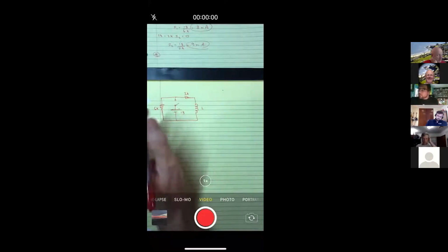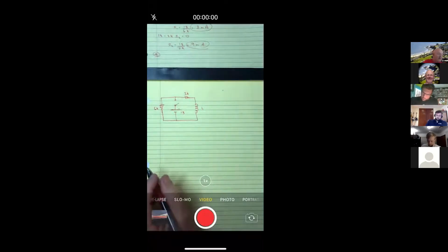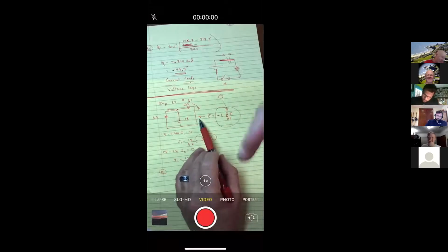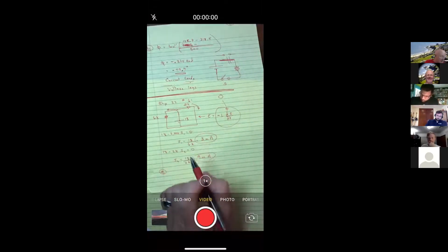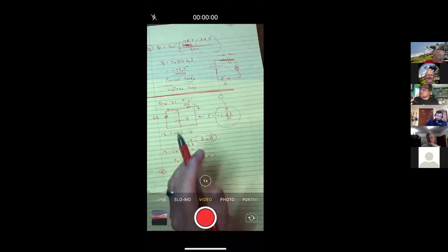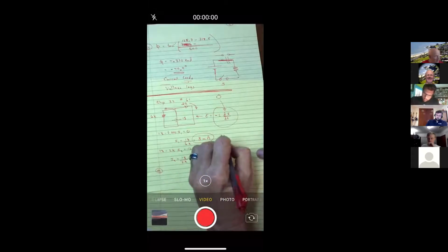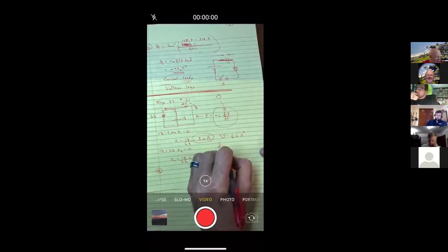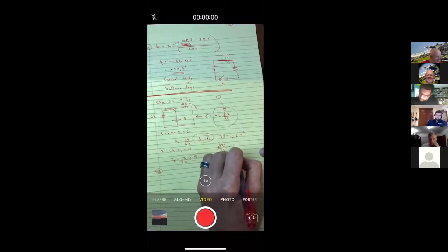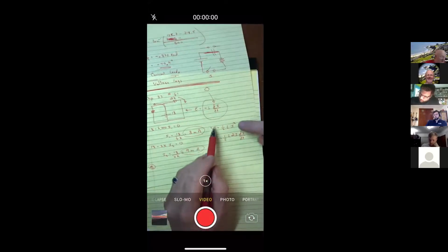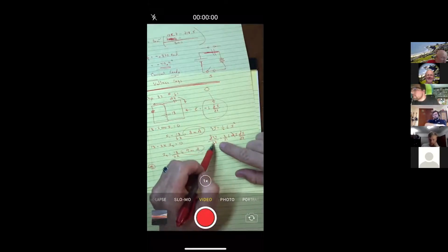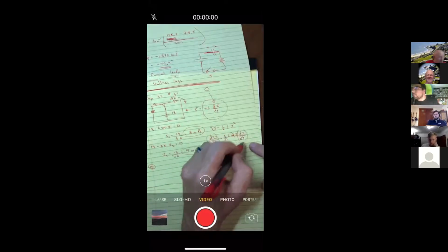This is kind of what I was referring to earlier about the inductor. I made the argument after a long period of time, but I also said after a short period of time, it would make a voltage. And here's the idea. We got this from the energy in the inductor, which says you can't really change the current instantaneously in an inductor because of this fact. If this is the energy, then changing the energy quickly would need a lot of power. So you would need a lot of power in order to change the current.